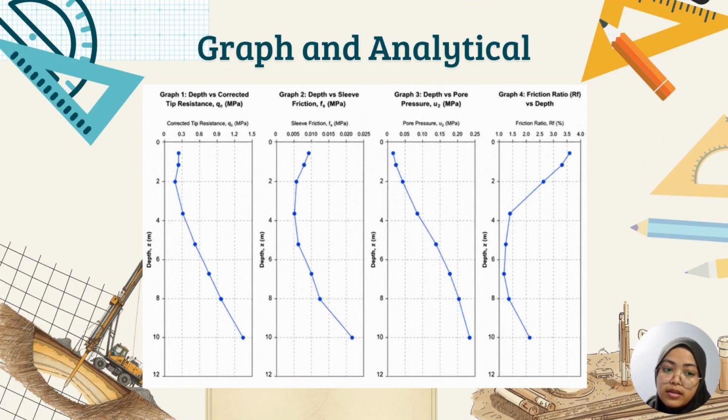This value indicates the soil at the 10 meters depth has significantly higher strength compared to the upper soft clay and peat layers. Based on this calculation, the corrected cone resistance, friction ratio, and undrained shear strength all indicate that soil strength increased with depth. The layer at 10 meters depth provides a stronger bearing stratum, and is therefore more suitable for supporting foundation loads.